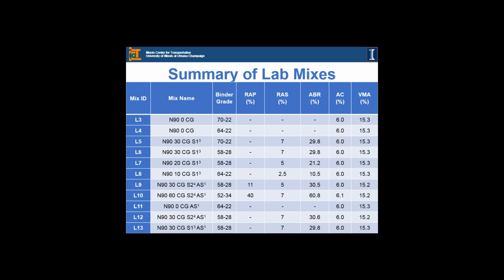We really achieved this mix by adding 40% RAP and 7% RAS. It's really an extreme mix that you can imagine in the lab, that was also designed in the lab for us to characterize its performance characteristics.